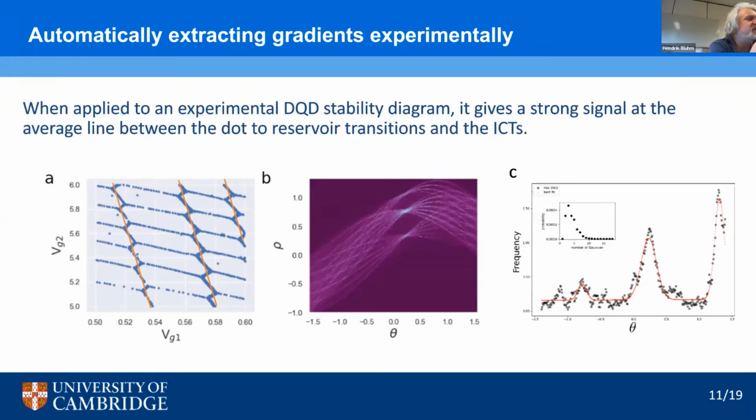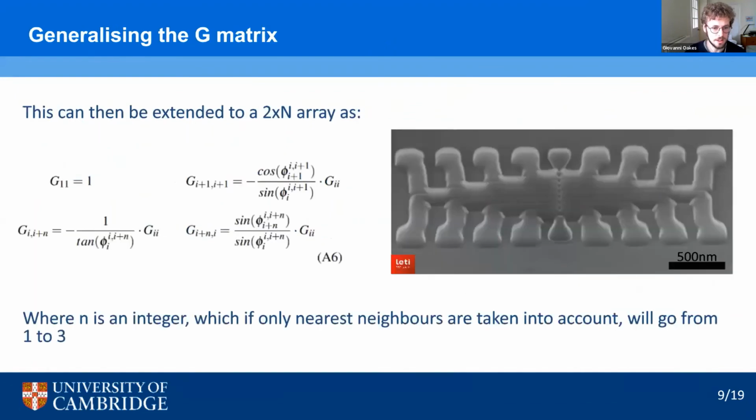So I was curious if you could comment how this method compares to the idea of just measuring how much any charge transition at one particular point shifts if you change all the other gate voltages. So basically a more local cross capacitance measurement. Basically, you do a line sweep.